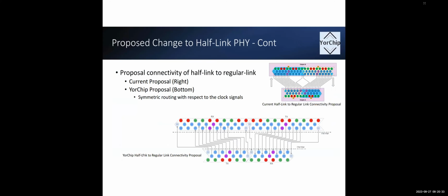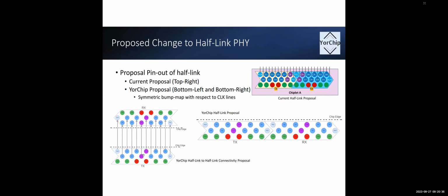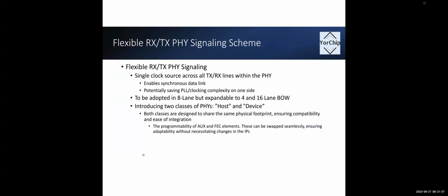Yeah, understood. I guess the trick here is that effectively it's not really clock forwarded anymore, in the sense that there is one root clock for everybody and there's a path you can define, but the conceptual delay in that loop is much larger than it would be in a normal clock forwarded situation. Exactly. There's a little bit more intricacy involved. Okay, got it. I should have placed this picture down there so that it makes it easier.